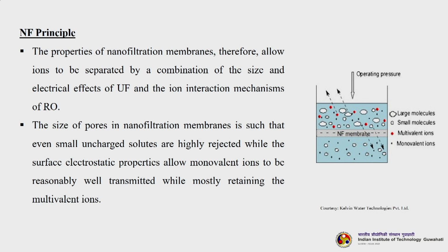The properties of nanofiltration membranes therefore allow ions to be separated by a combination of the size and electrical effects of UF and the ion interaction mechanisms of RO. That means NF actually works on the combined principles of UF and reverse osmosis. UF is basically a size exclusion membrane process, though charge-based separation also has an effect. However, in RO the ionic interaction plays a major role. So, in NF all these things play a role while rejecting a solute or permeating the water.